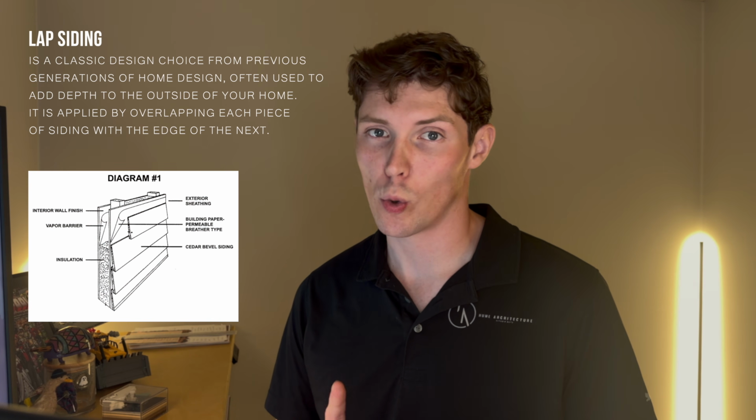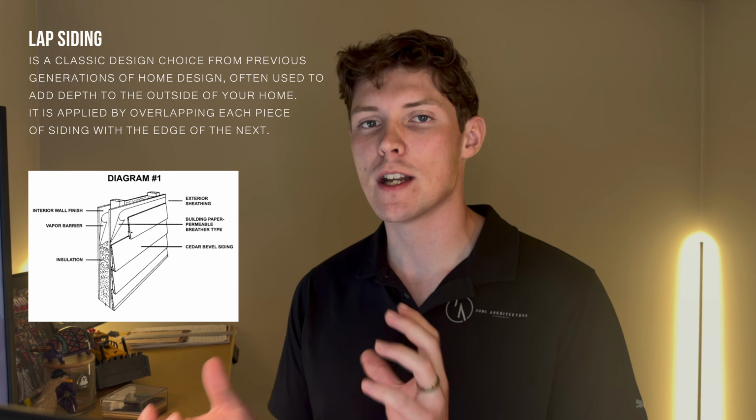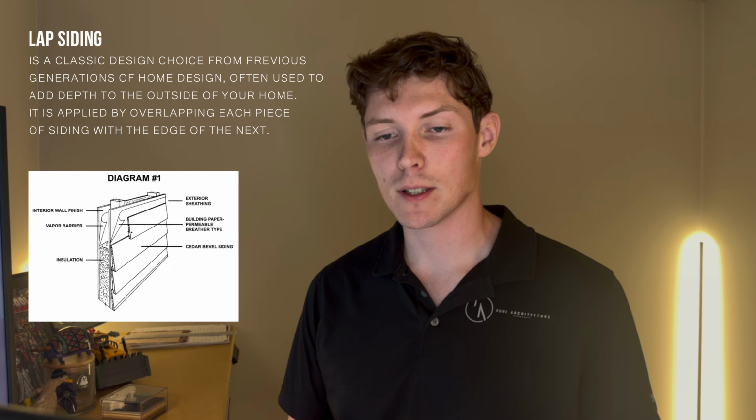If we were to stay as simple as possible, we won't pick out exact materials. We'll just be rough. If you want lap siding or just horizontal siding versus vertical siding, we can call those details out. There are a few different things that will change for the actual wall construction, but typically we can leave that as generic as vertical or horizontal. Similarly with a roof, we can leave that as asphalt, we can leave it as metal. We don't need to pick out the exact manufacturer, the exact color, the exact style, but we can go as in-depth as possible with those things.